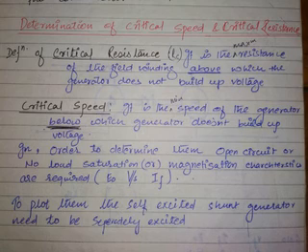Even though there is residual flux, if the build up of voltage is still not taking place, then definitely the field is not properly connected to the armature. Then you will reverse the field winding, because the residual flux got erased away. Do the field flashing, again reverse the field winding, connect it, and start the machine. So these two are empirical, or trial and error based methods. By seeing the machine, you can simply judge and automatically rectify them.